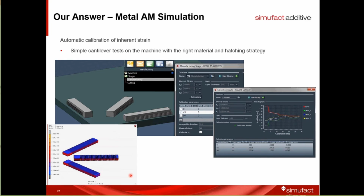We take that information and perform a little design of experiment simulation with finite elements, and we back calculate what the inherent strain is for your process, your machine, your powder, your parameters. We can do that relatively quickly.